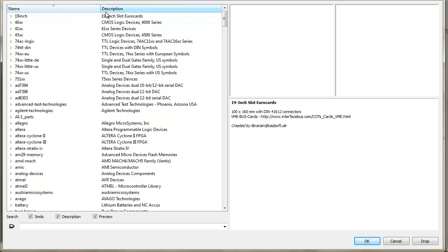A lot of people create parts, they just kind of have fun doing it and upload, but they never actually verify them. The SparkFun library that tends to be out there, people use that one a lot. That has a lot of verified parts, but it also has a lot of unverified parts, and some of the parts are just plain wrong. But they do warn you about this, but regardless, people make them anyway. So that's why I like to either create my own parts or verify them before sending them off.